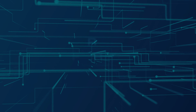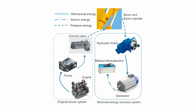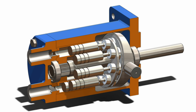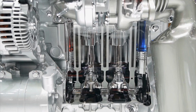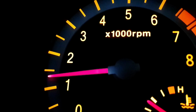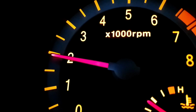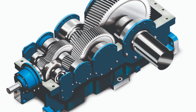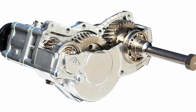The primary source of force in an excavator comes from its hydraulic system, which converts engine power into powerful mechanical motion. In a typical hydraulic excavator, the diesel engine acts as the primary power source and drives one or more hydraulic pumps. The engine crankshaft usually rotates at high speeds, typically around 1800 to 2200 RPM, while hydraulic pumps are designed to operate efficiently at a specific speed range. Therefore, the pumps are often connected to the engine through a pump drive gearbox, which reduces the engine speed to the required pump operating speed.